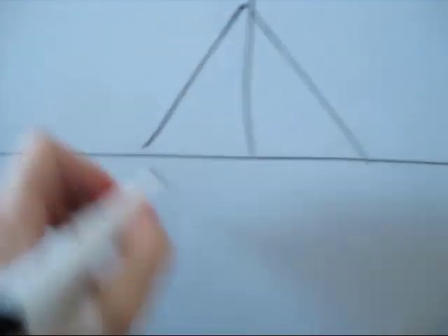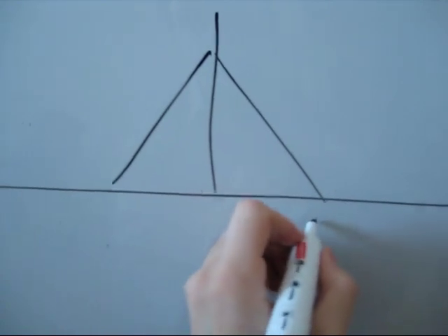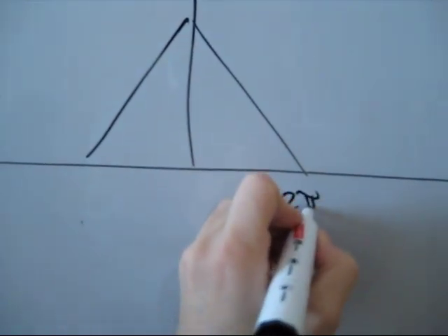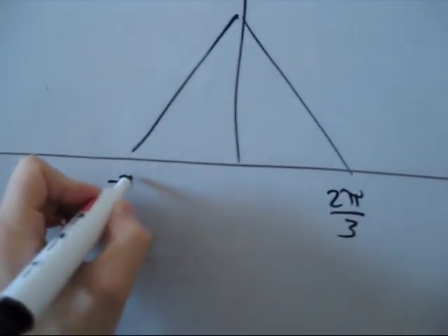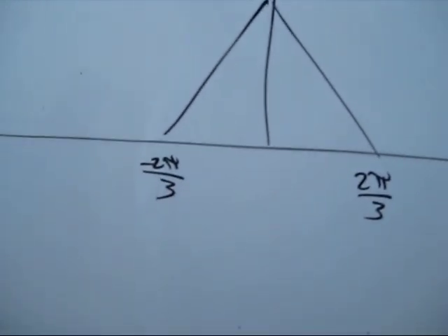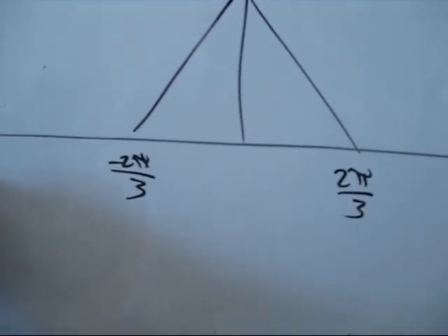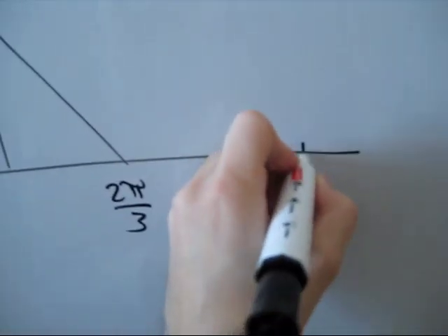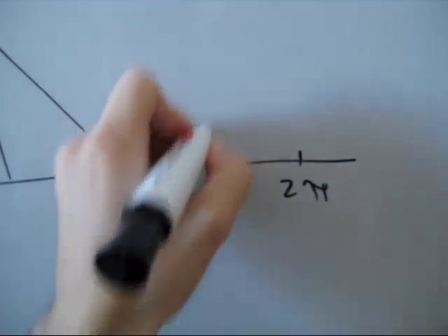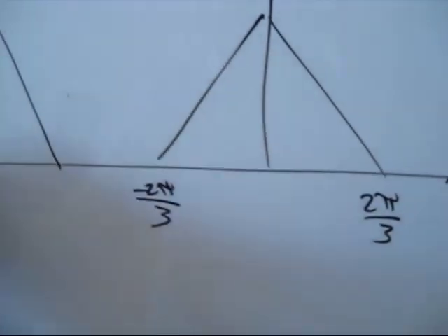And so when you sample that, again, you're going to introduce your replicas. So here this is going to be at 2 pi over 3, minus 2 pi over 3. And of course the replicas are at multiples of 2 pi, right?